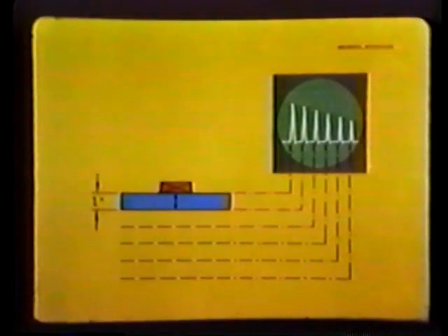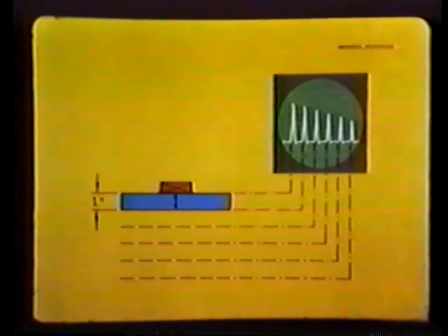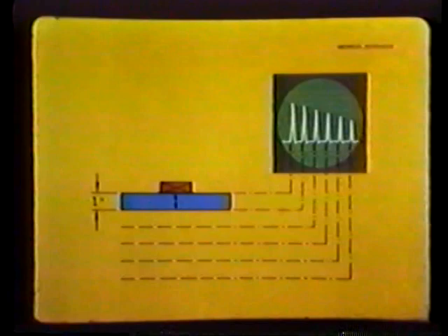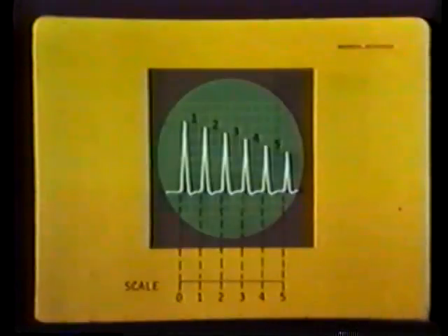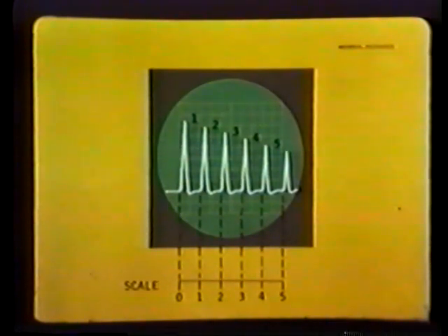You should also know that a specimen with parallel front and back surfaces will yield several back surface reflection multiples, depending on the instrument sweep or range setting. These multiple echoes are caused by the sound beam bouncing back and forth in the material, their amplitudes decreasing with increasing multiples. This display shows 5 thicknesses, each pip being exactly the same distance apart. By using several thickness indications instead of one, accuracy is greatly improved.